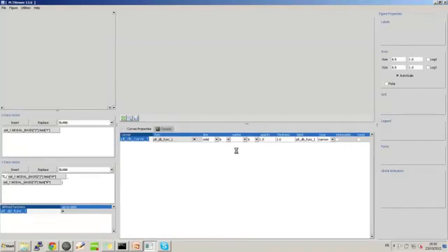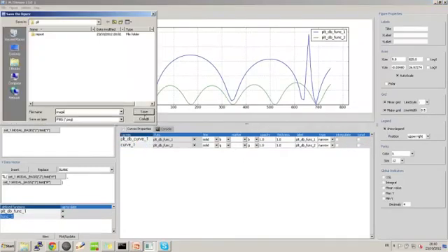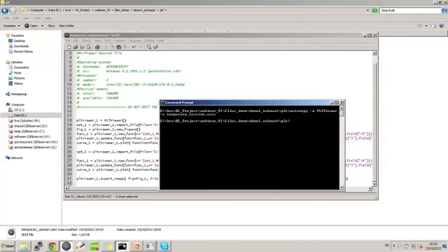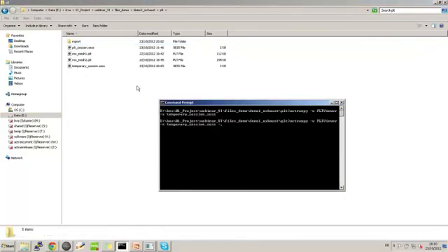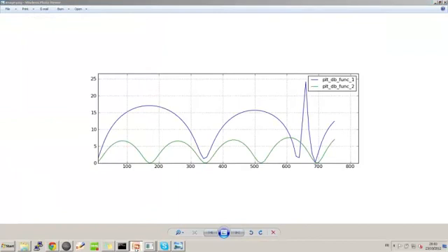Now what we could also do is, for instance, save this as an image. So that's what I am performing here, and you see that I could also copy paste this line over here and add this directly within my session file in order to produce an image directly the next time that I am relaunching this session. And what we will perform right now is the same execution, but in non-graphical mode. So before that, I'll suppress the image that was produced by Actran, and I will now launch the same command line, so Actran pi minus PLT viewer for the PLT viewer, minus X my session file, and then minus N for activating the non-graphical mode. This will produce automatically an image that will appear in here that is representing the same image as we had before. Okay, so this was our live demo.